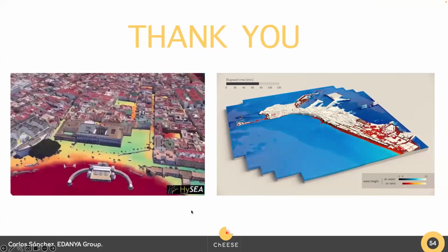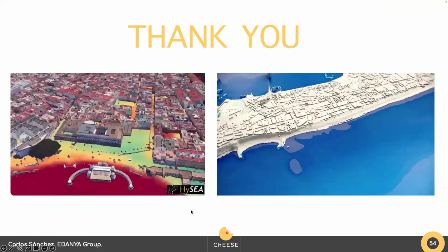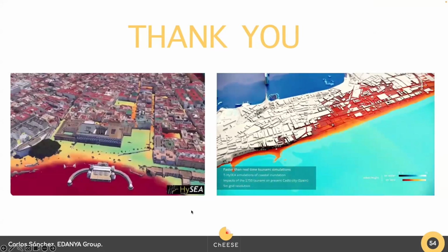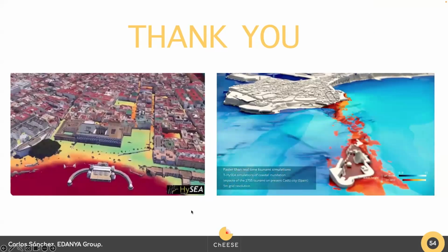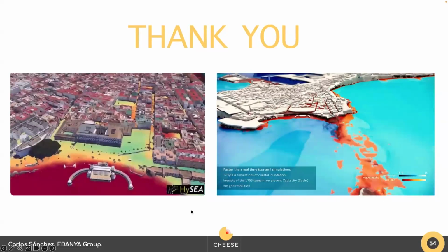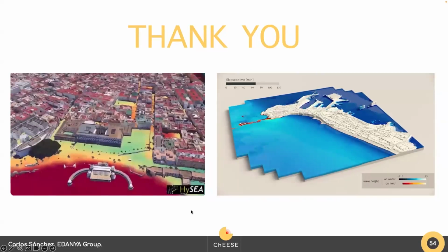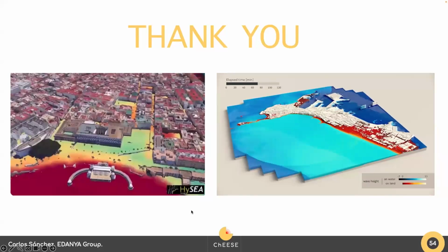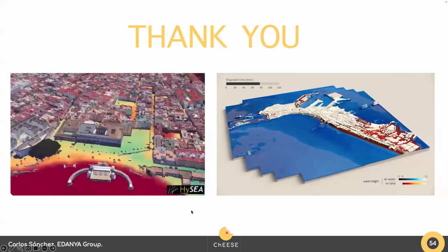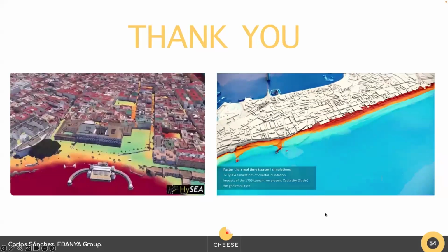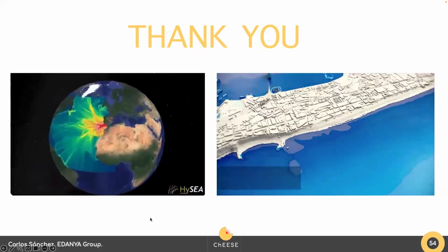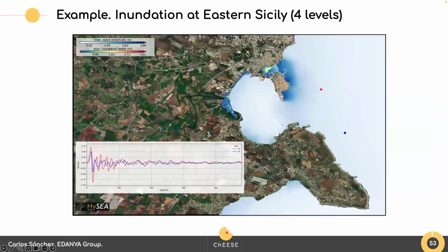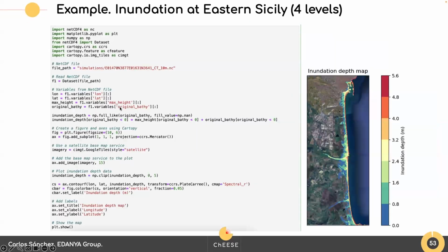Well, it is better to use the deformed bathymetry, because in reality, if you apply a big event using Okada parameters, most probably you change your sea floor bathymetry. So in the last script, let me move back here, you can use the deformed bathymetry in order to calculate the inundation depth.